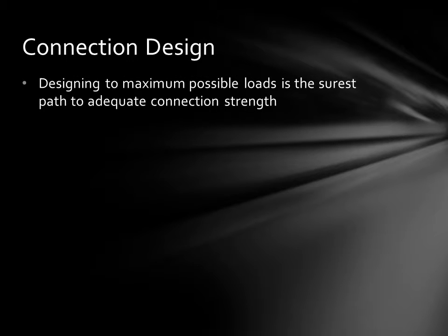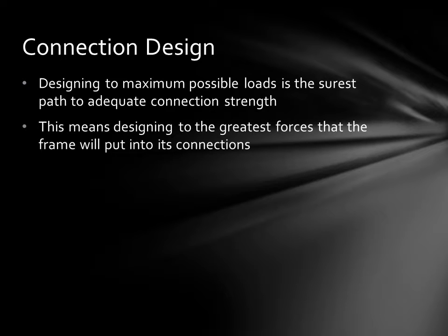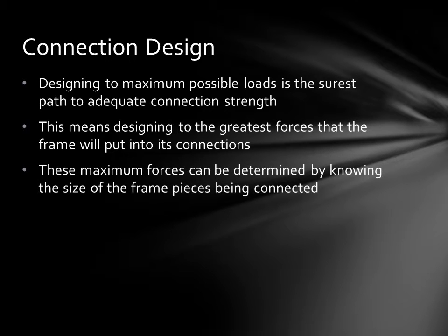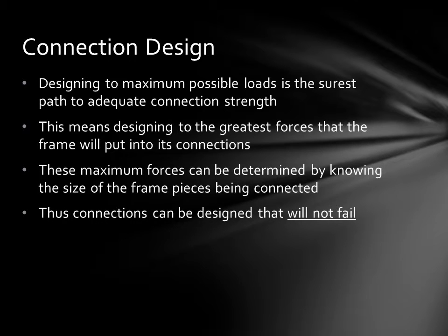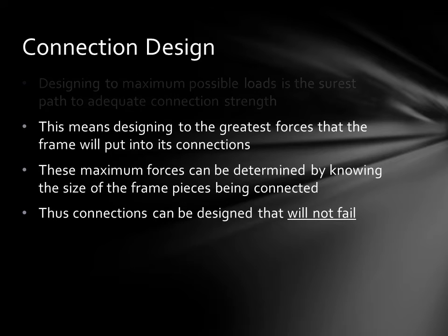Designing to maximum possible loads is the surest path to adequate connection strength. This means designing to the greatest forces that the frame will put into these connections. These maximum forces can be determined by knowing the size of the frame pieces being connected together. Thus, connections can be designed that will not fail.